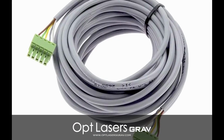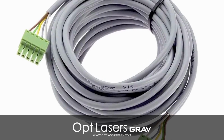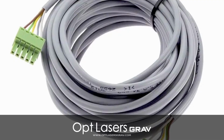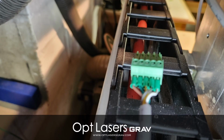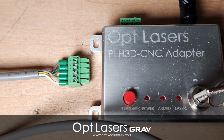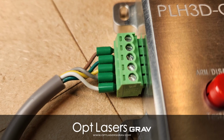The next cable we're going to install will have a 5-pin connector on each end. This cable will connect the laser head to the CNC adapter. Start from the laser head. Thread this wire through the cable management system until you reach the CNC adapter. Once the cable has been threaded through, attach to the left side of the unit.